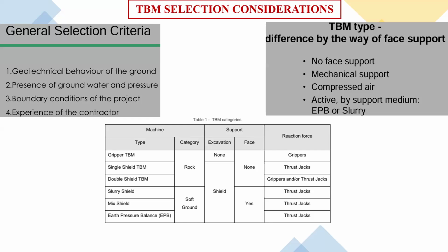So it is a very favorable choice for an EPB machine, because we can use an earth pressure balance machine. If I go to Chennai or Bangalore, we mostly prefer a slurry machine because here the groundwater table is very high and we are expecting a combination of sand and some portion of rock or boulders. So mostly we rely on the slurry machine with hybrid mode. So groundwater behavior, or groundwater presence, or how the groundwater can flow inside the machine, and also the geotechnical characteristics of the ground mostly predominate in the type of machine we select.